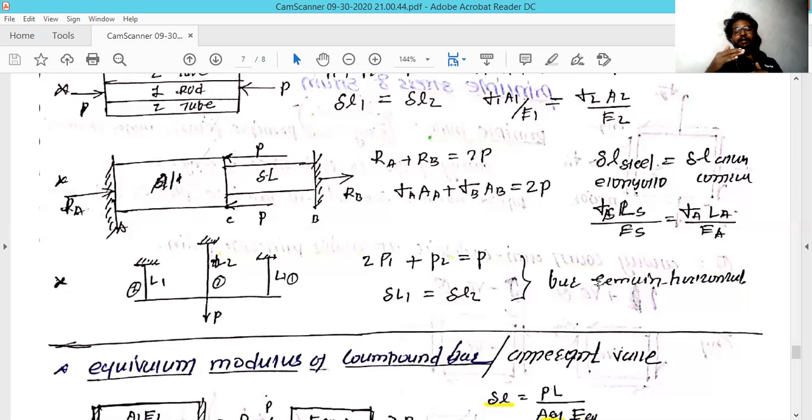If the initial and final condition of the rod remain horizontal, the cables at both ends and at the center will have elongated by the same amount. So you can write that the change in length first equals the change in length second.